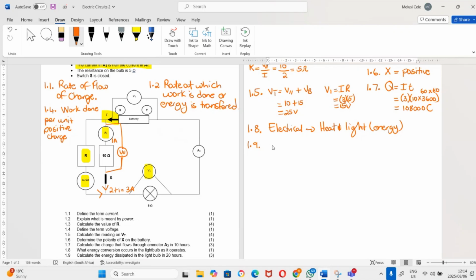The electrical energy, don't forget, is the input energy, right? So that's the input energy. And so if we assume that what is input energy is actually what comes out, then we could use the formula W equals, is it VQ? Yeah, it is VQ, which can be further broken down into V multiplied by IT. So basically the charge is equal to the IT part.